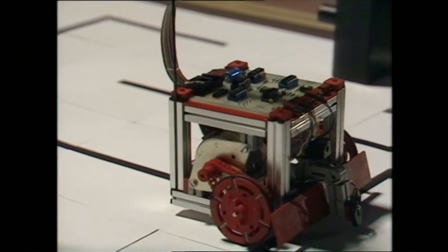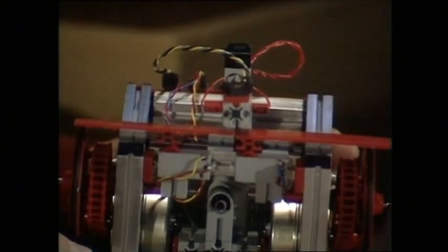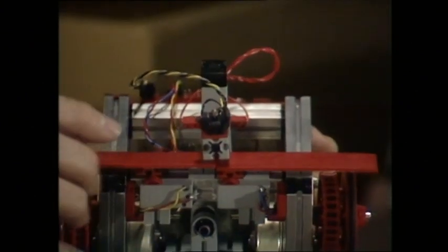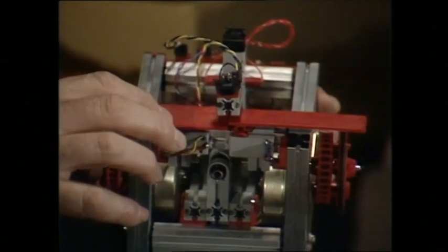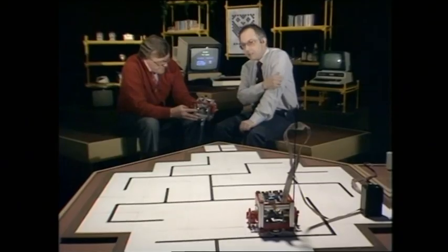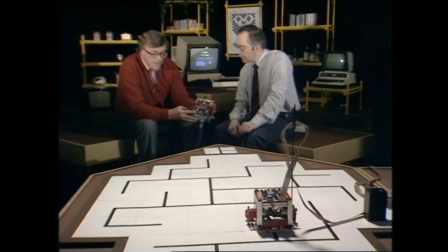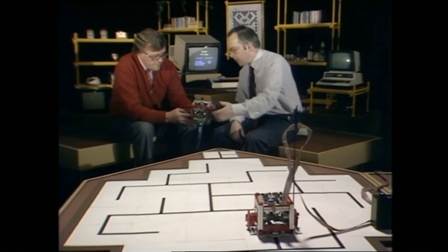So I've got another buggy here. Let's have a look at this one. Well, there are 2 digital sensors and 2 analog sensors. Well, clearly the buffers are the digital sensors, that's it. And it feeds out into the computer there. We can hear it give that. That's the right-hand one. There's the left-hand one. Right, and it uses those to sense when it's hit the end stops, to know if it's actually touched something. Those are digital. They're just working micro switches underneath.